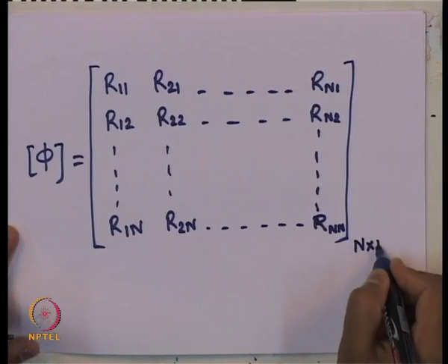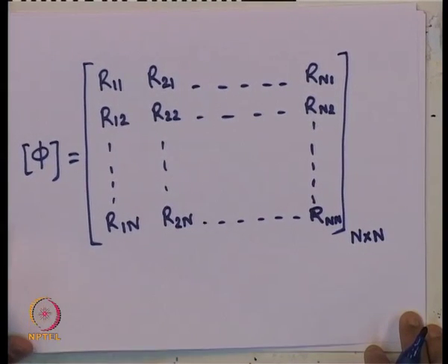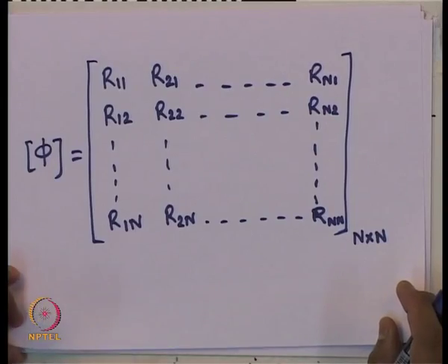So, this will be a transformation matrix of size n by n, as we have mentioned. Like this, using the transformation matrix, for any coordinate system, whatever equation of motion we got, if all the matrices are coupled or some of them are coupled and some are uncoupled, we can transform them to our natural coordinate system, where all matrices are uncoupled or diagonal, and then we can solve it for the n degrees of freedom, which will be obtained from its natural frequencies, and then the corresponding solution can also easily be obtained.